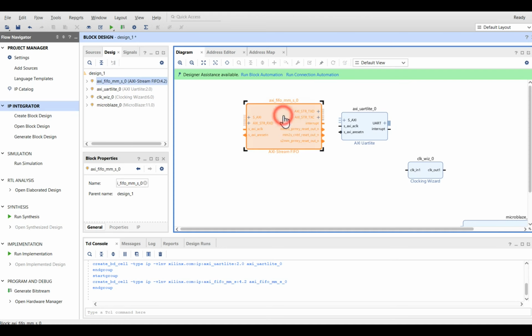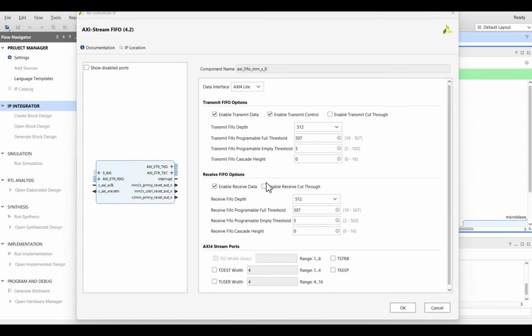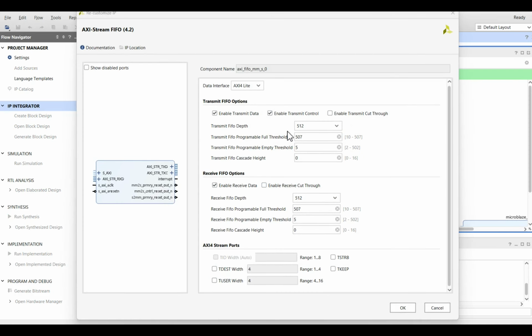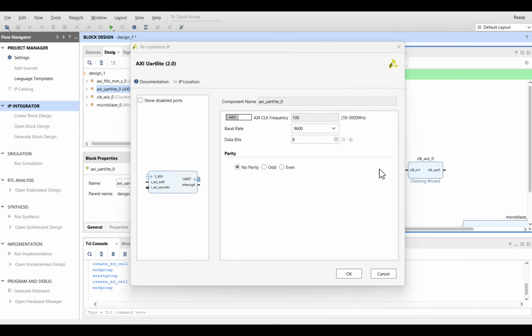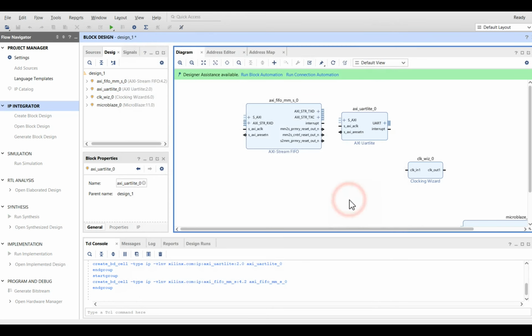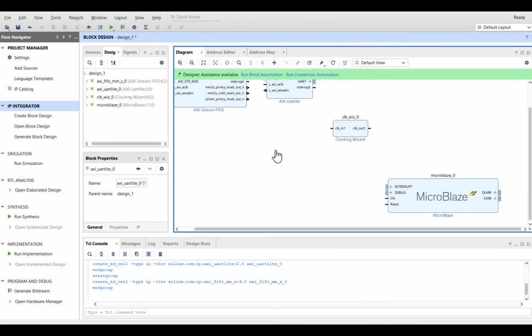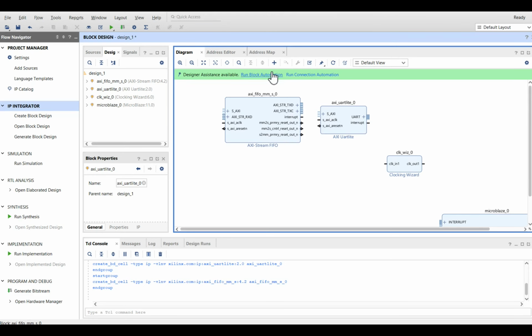However, note that in a larger FFT project, if we wanted to increase the length of the FFT, we would need to change the FIFO settings to have more entries be stored inside to accommodate for a larger FFT. But since we are only doing an FFT that is of length 64 in this project, we can leave the FIFO in its default form.